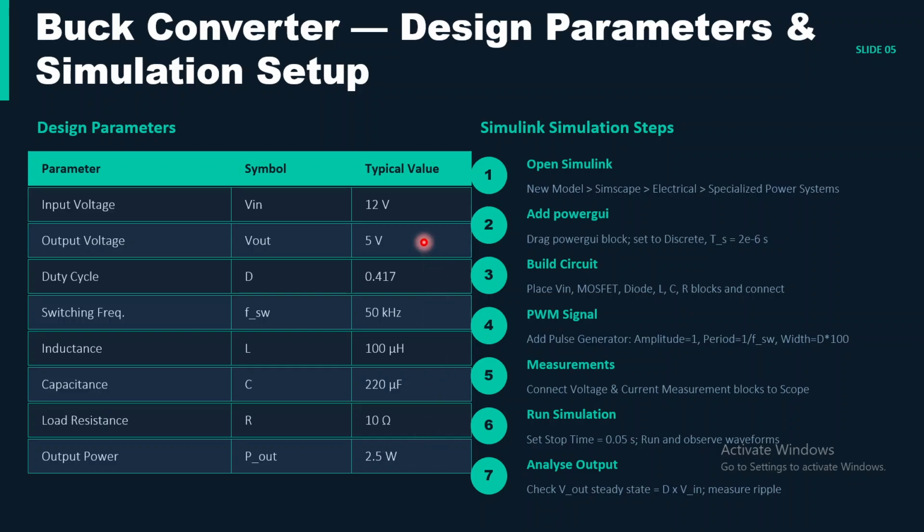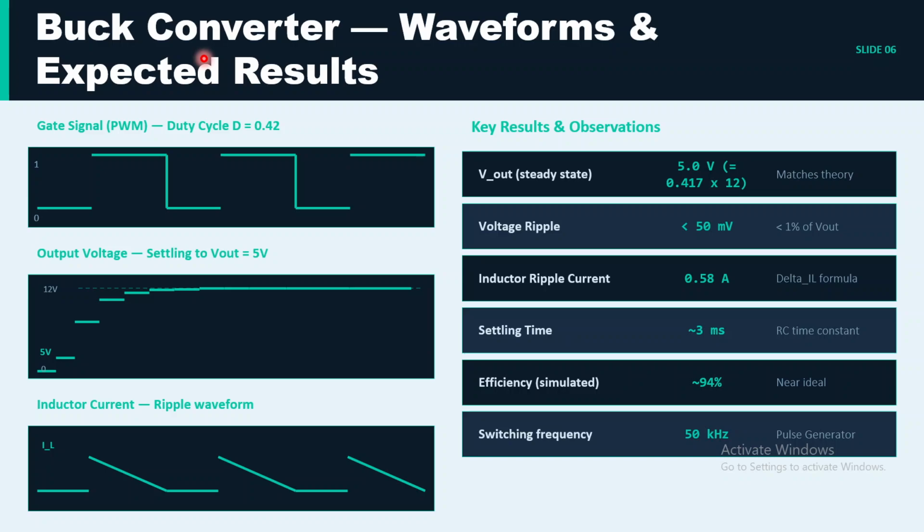When you multiply voltage into current, you will get the power. These are the steps you need to do in Simulink. I will show it live, building the blocks and connecting the resistor and capacitor to the circuit. You will get the basic buck converter circuits online, so you can check them out. This is the output side, so we will obtain the graph at the output side.